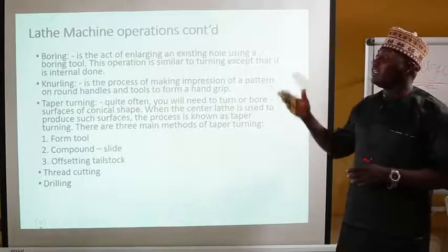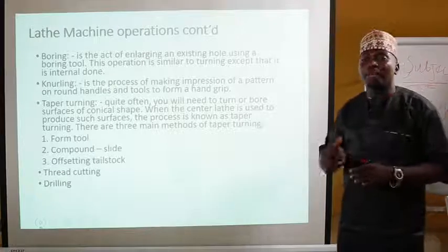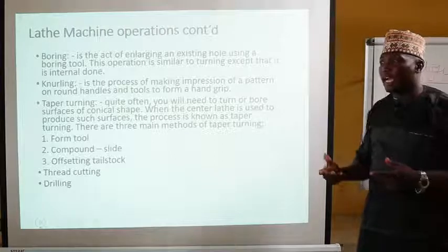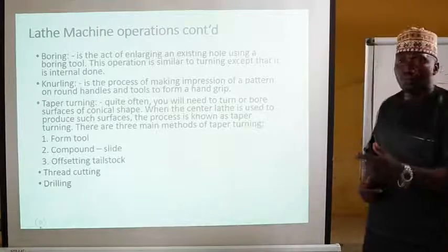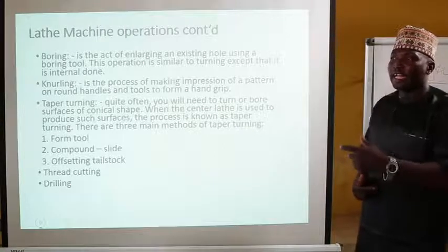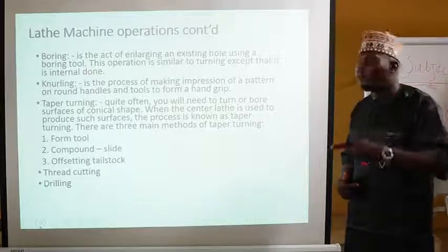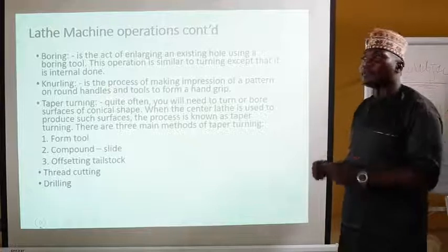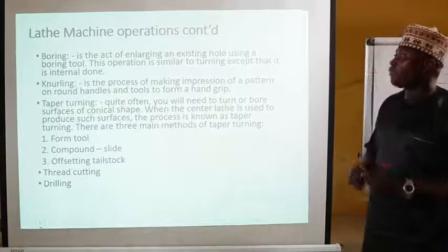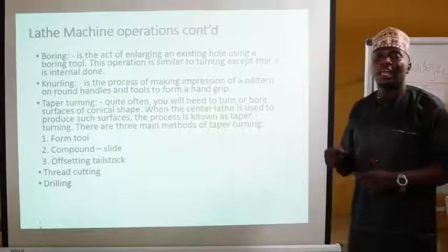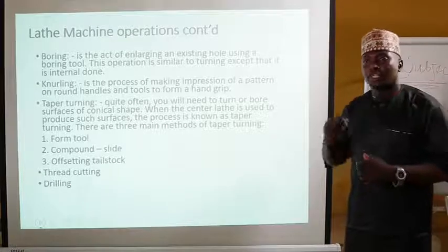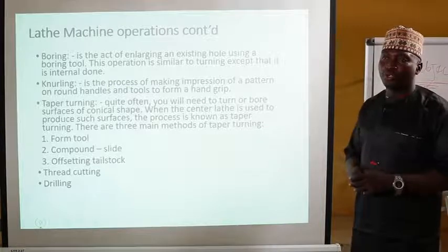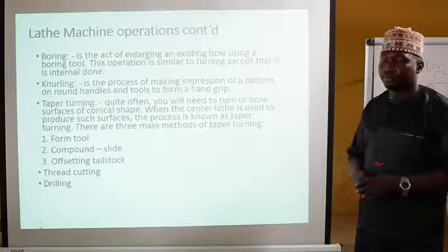Parallel turning only reduces the external diameter, but the movement of the tool on the carriage that gets in contact with the revolving workpiece at the headstock center is exactly the same as in boring operation. And of course, each of these has a particular special tool, which is the boring tool.